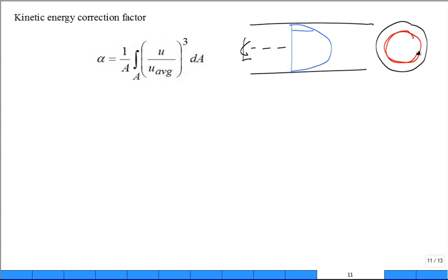That little ring of fluid has the same speed if it's symmetrical flow, and it is. That ring is at radius lowercase r. The thickness of the ring is dr. We did the conservation of mass to get the equation for the average speed; now we're redoing it for kinetic energy. Hopefully this is almost the same song, but slightly different words.